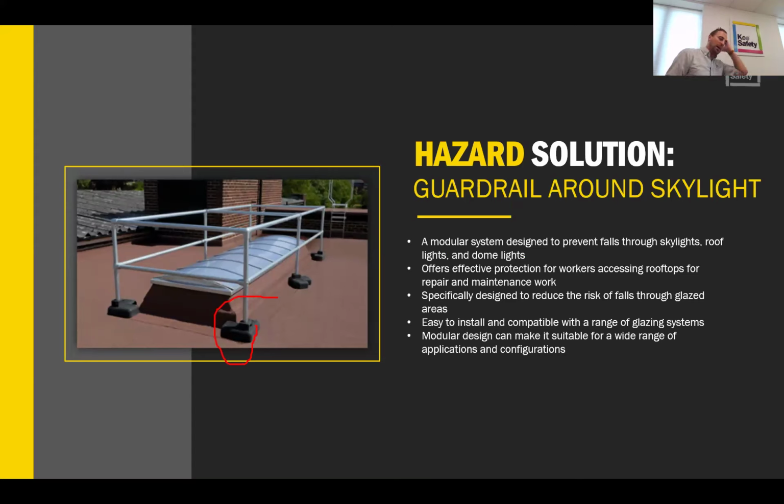So thinking about your facility, think about the skylights. Are they protected? Do not believe, hey guys, we got fall protection on our skylights. Oh, our skylights are fall rated. They probably aren't. If you're really curious, go through and check the manufacturer. But if it's got a bubble on it, chances are it's a plastic PVC or just a plastic polymer dome that's basically being broken down in the sun that needs to be protected.